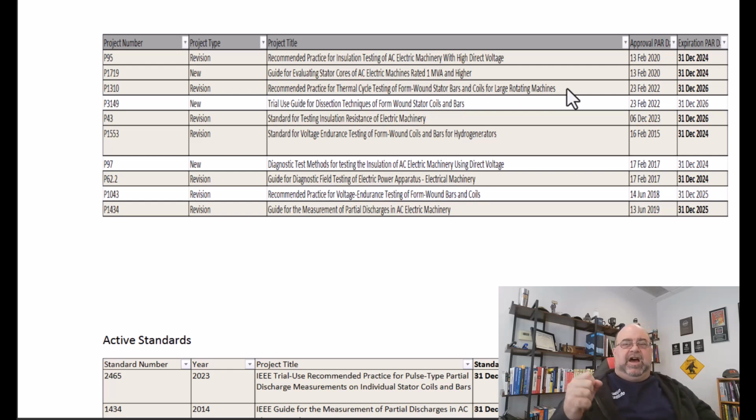And if you say, I want to use 1310, or you must use 1310, the implication there is that could mean that you are going to perform all those tests, and you might get false positives or negatives on the condition of the machine or coils. So often those tests are performed, but they're performed and then recorded for later information. So that one was interesting. I'll probably cover some of these independently a little more at another time.